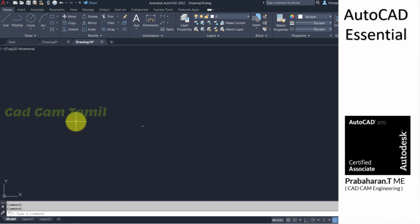Why is it like this? It's very simple. Here the drawing area is very big, that is why your 50 mm is very small. Here your drawing area, that means your drawing sheet, is very small, that is why your line looks very big. So it should not be like this. Before you draw, you have to decide the size of your drawing, or on what paper you are going to draw.